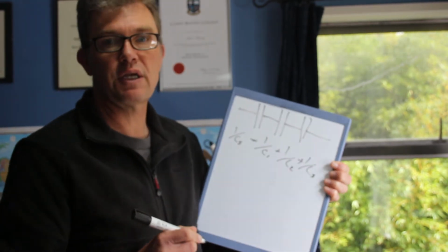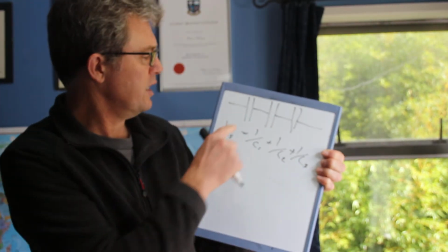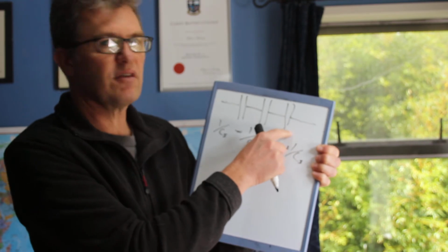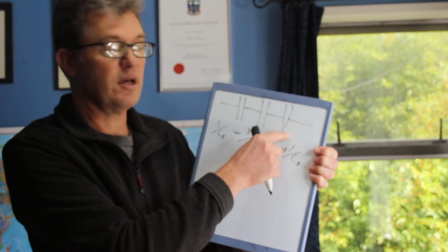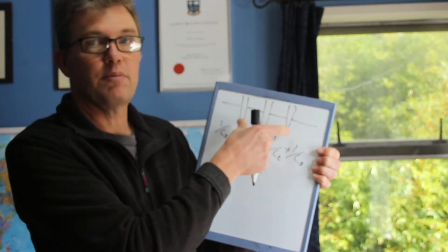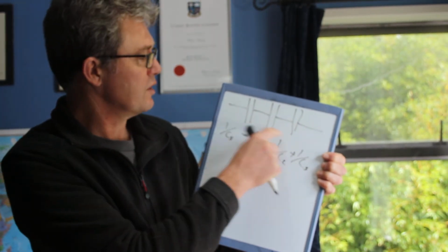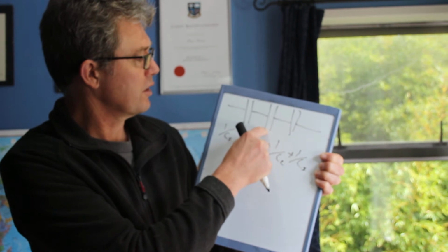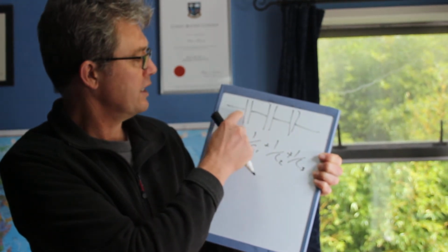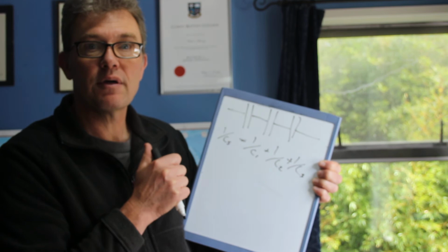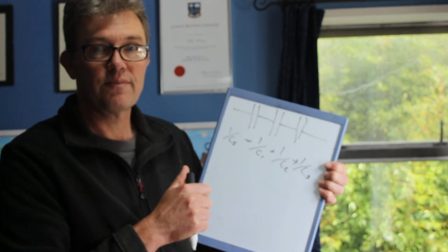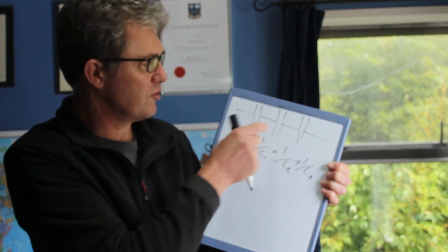You can show it mathematically, but basically the idea is each of these gaps is effectively just making one capacitor with the same area but a really big gap. You can imagine the ones in the middle do nothing, and you've just got a plate here and a plate there and a bigger gap between those two plates. So effectively you've got one capacitor with a bigger gap.